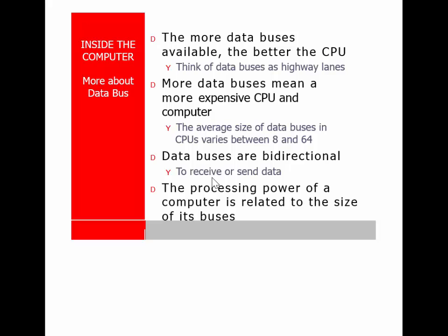The original IBM PC, which came out in 1982, had an 8-bit bus externally, but inside the chip it was 16-bit. It was a very confusing microprocessor to teach, because it's 16-bit when you deal with the internal software, but 8-bit when you deal with the external hardware.